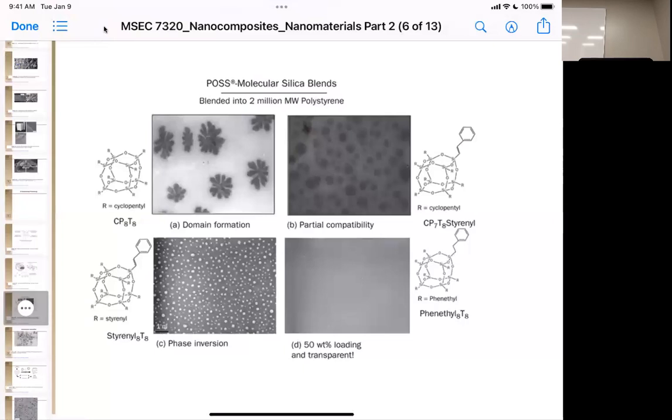Now, by taking that out and adding styrene to it, hey, polystyrene should dissolve in styrene, right? Well, again, we have the styrene, and there's eight of these hanging out there. Yes, that would be very compatible with the monomer. In fact, it probably dissolves very well in the styrene monomer, but the polymer actually doesn't have the double bond and the rigidity that the styrene has. So let's space that out a little bit more, and instead of having all styrenes, have just a few styrenes. Well, that helps a little bit, but it doesn't take it all away.